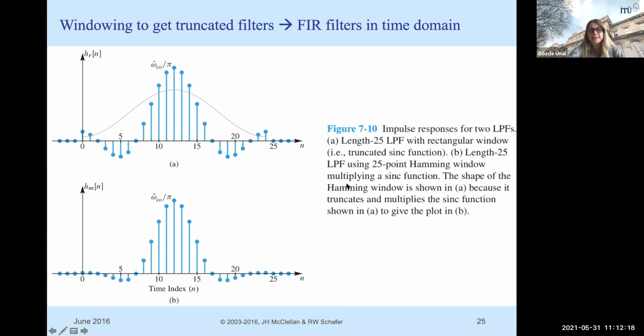So you see in this case it suppresses, reduces the amplitudes of these border values, okay? So in that case, the truncated sinc is multiplied by a Hamming window. So those border values are also closer to 0. Do you see what I'm saying? So this slide, guys, shows the difference between multiplying the sinc by a rectangular window and by a Hamming window.